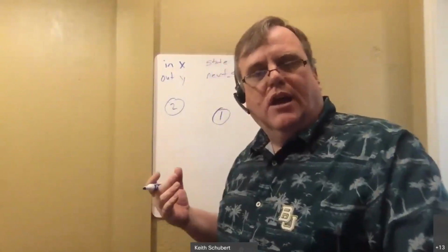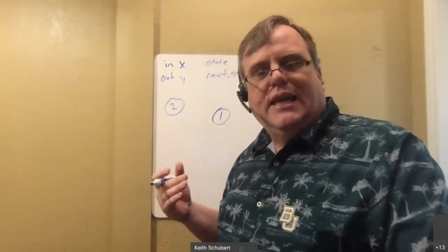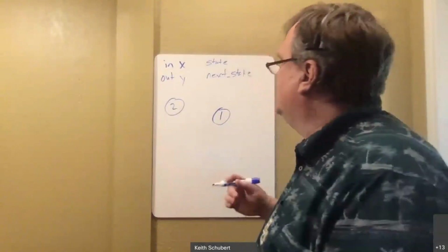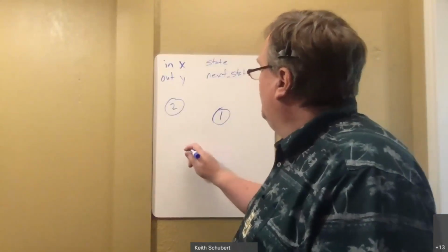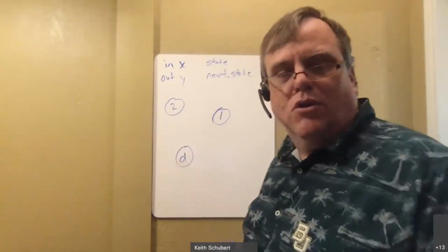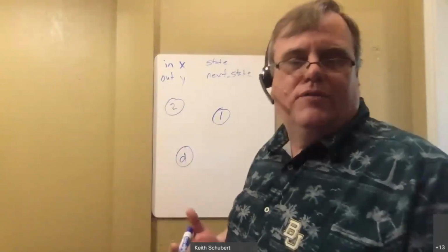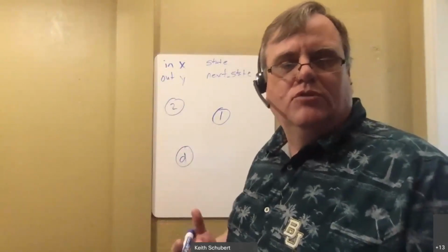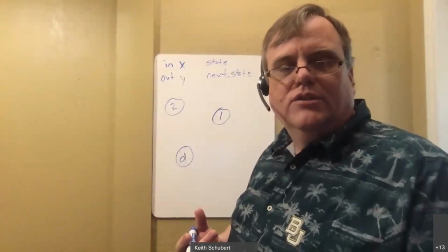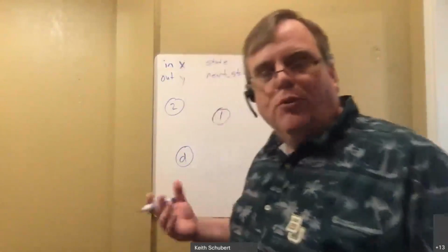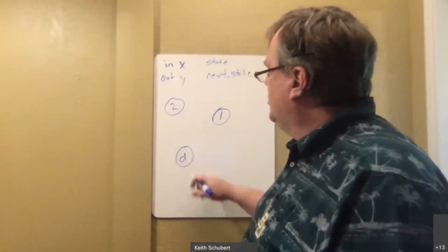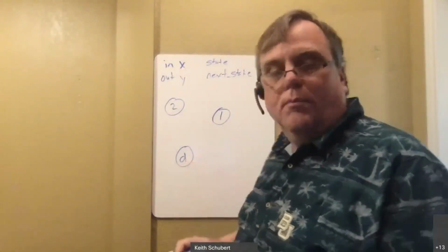So let's see. I've got inside the case statement a 2, a 1, and a default, which means I've got 3 states. So I'm going to put 2, a 1, and my default, which is probably going to be state 0. But we'll have to take a look and see what comes up from each one of these. There should be nothing that's a 3 on this, or 3s get folded into the default. So I'll just leave it this way because this could be 3 or 0 or both.